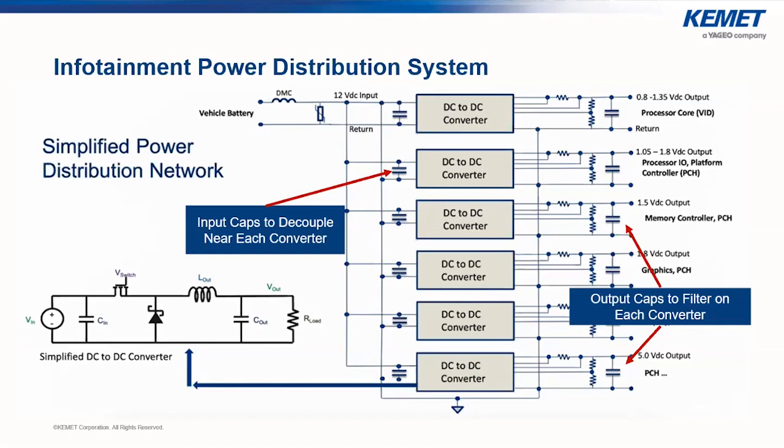It creates inertia for the electrons that are flowing, so it wants to keep them going at the same rate, so that your current doesn't change significantly over a short amount of time. It just keeps on going. And then, of course, there is a bulk filtering capacitor that is keeping that voltage very stable. So you're keeping a nice current and a nice stable voltage on the output feeding the load. That is, I guess, the basic building block of your DC to DC converter.